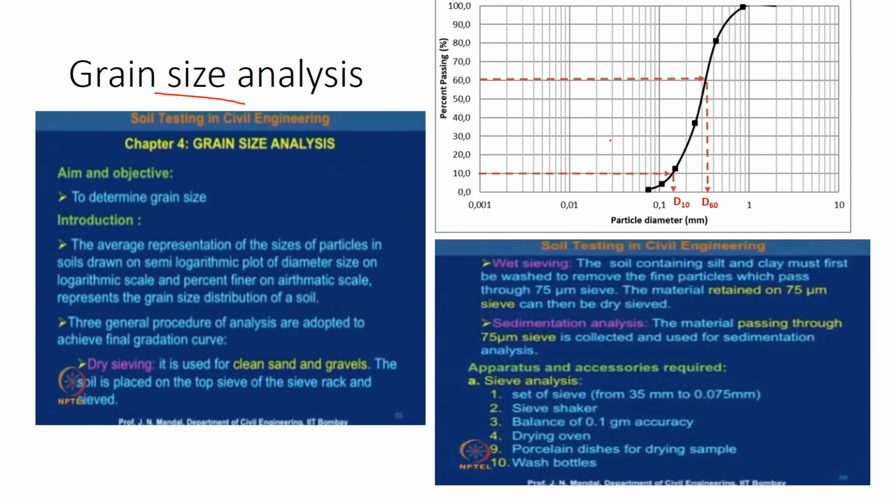You have to be very careful in this. For liquid limit and for grain size distribution, we go for a semi log graph. We don't go for a normal graph. Many of the students, even here, if I take an MTech class, people forget that. Only if you plot on a semi log graph will you be able to get the curve properly. Does anyone want to know what a semi log graph is? I hope everyone knows. If not, please let me know.